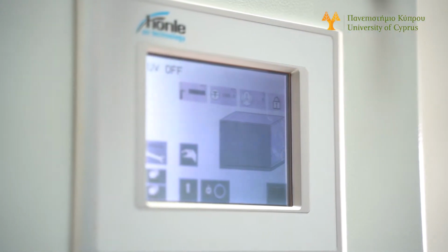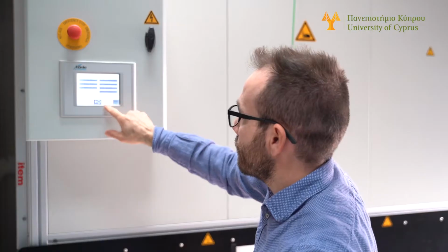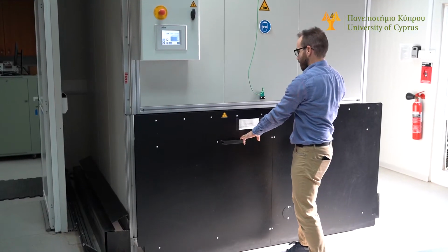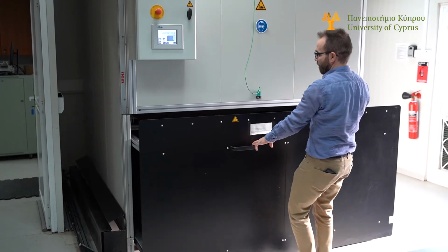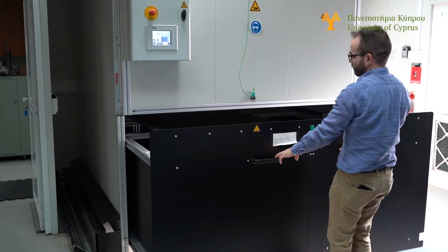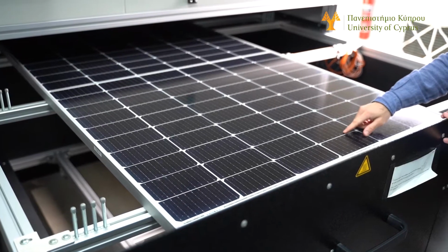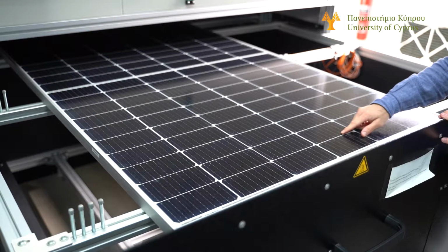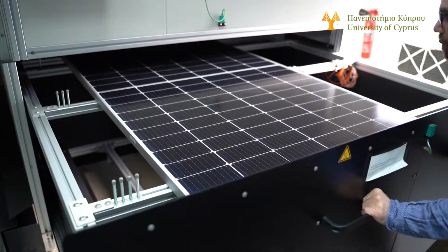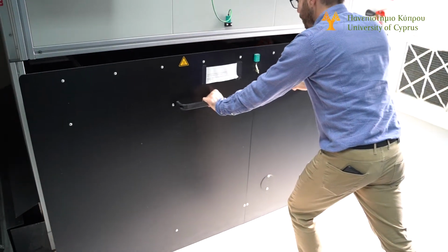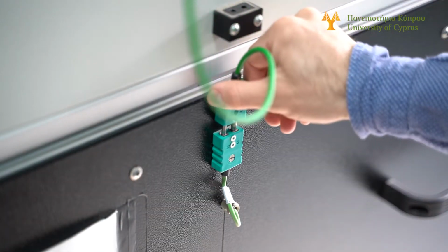This device is a UV sun simulator that produces UVA and UVB radiation. Using this device, you can expose the photovoltaic modules to a specific amount of radiation according to the standard that is followed. Also, it gives the capability to change the radiation level in order to perform non-standardized tests in the case that the researchers want to evaluate the device under test in different conditions.